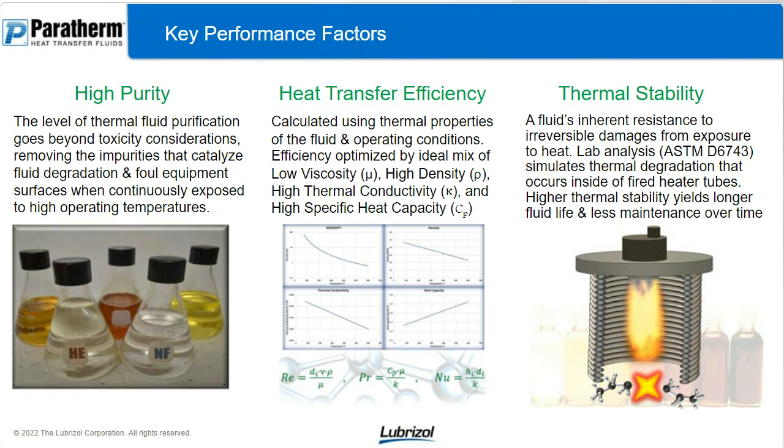This happens over the course of 500 hours for that ASTM test. And then you measure all the same properties and how much degradation material there is and how much the fluid broke down afterwards. It gives you a great indication, and we've verified a lot of this and justified this test with our experience in the field for doing this for 35 years. And the higher thermal stability will give you a longer lasting fluid, but even more importantly than the longer lasting fluid, it gives you less maintenance over time, less wear and tear on your equipment, and an overall total life cycle analysis that's going to be better.